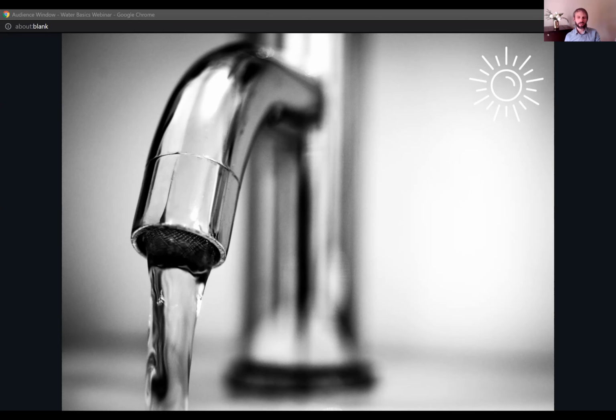In the kitchen, you're kind of looking at 2.5 gallons per minute, 2.2, maybe 2. We're seeing a lot of 1.8s now, and again, we want to ideally see them down to 1.5 gallons per minute in the kitchen. And we've got the energy logo there because we want to confirm that you will also save energy at the water heater by using less water.